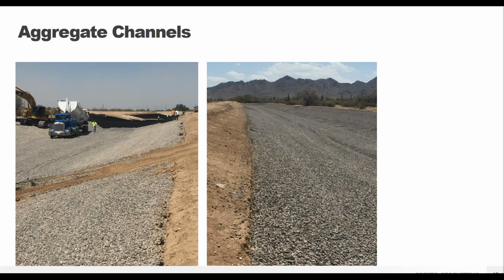They were able to use some waste rock from a nearby quarry, and really waste rock is not typically great quality, but that's okay. Like I said, you can use those salvaged or those site materials because you don't need the expensive stone. You just need something that meets your size requirement based on that regression analysis that we had talked about. So it really can help save on material and hauling costs if you have a local source of stone. So pretty easy.